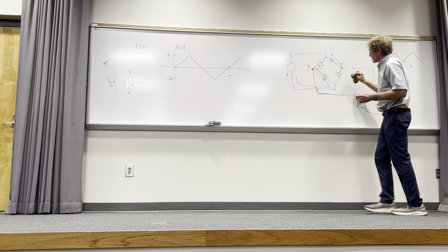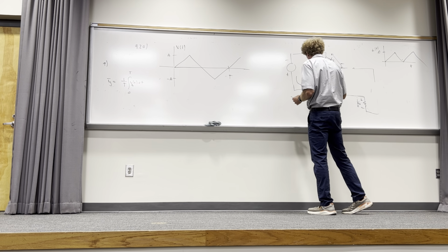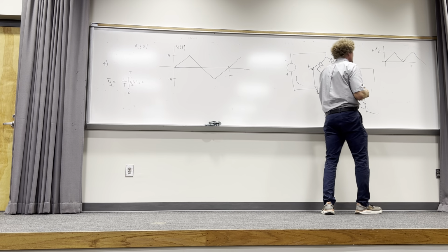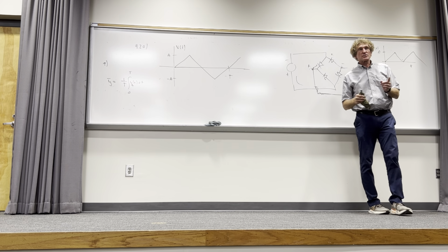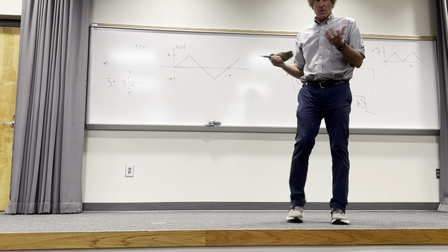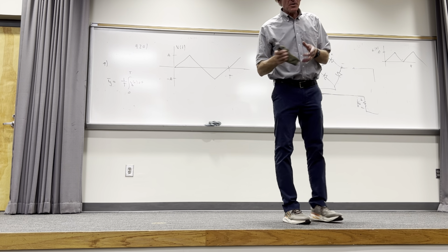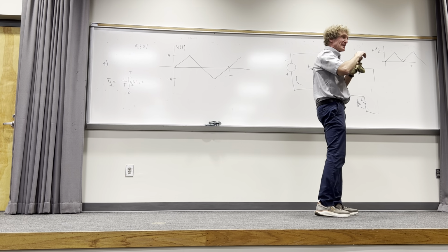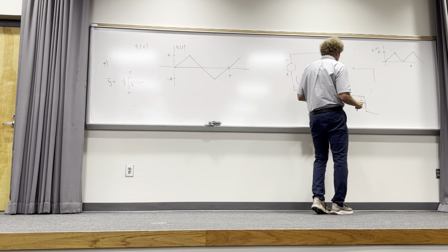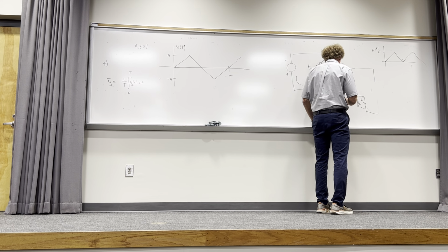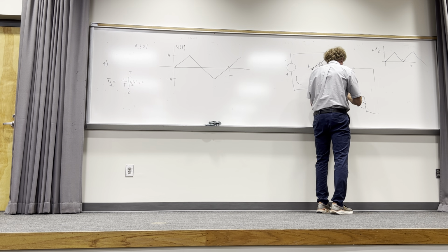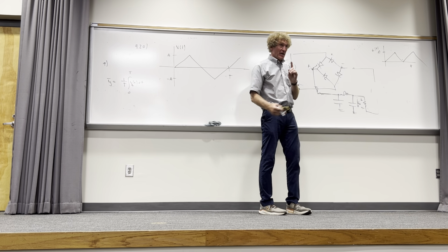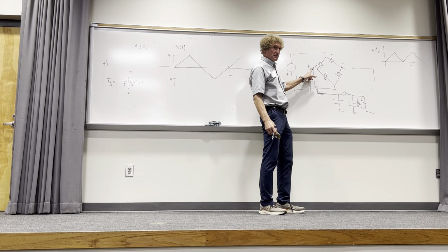What is really done in the real world with these things, because obviously this is not a DC signal, even though it is strictly positive, right? You all with me on this? So what they'll do is this, to make it a very flat DC waveform, they'll take some, I call them ginormous capacitors, but they're basically going to do this. They're going to put a capacitor here, and they'll put an inductor here and a capacitor here with respect to ground. Now, hear me on this. This is the side that's always positive. Y'all follow me?